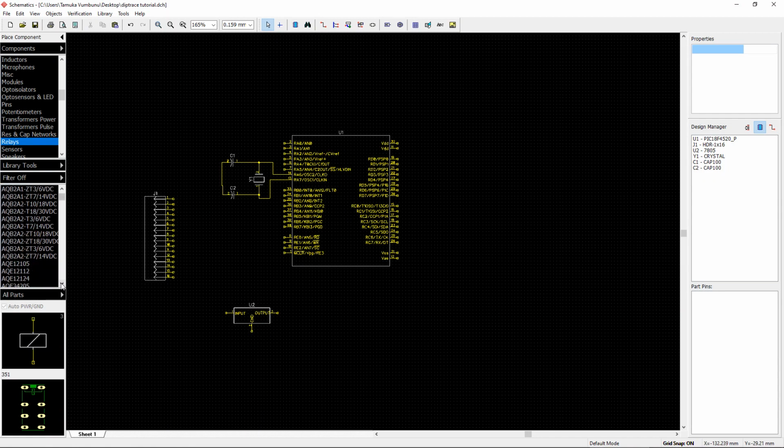Okay, now here's the thing. Some of these components you actually need to measure physically. You select the component right here, you see the dimensioning, then you check the dimensioning of the component physically to see if they match. Because if they have a slight variation, when you drill your PCB the component won't fit. I think that's obvious.